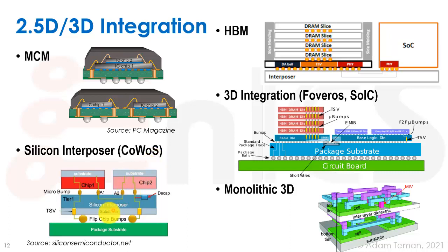So what you do actually is you have your package substrate, the regular package substrate, just like this one over down here. But on top of that, you put what we call a silicon interposer. So this is a VLSI chip. This would be in something like 65 nanometer technology or something, and it is not used for creating logic. It's only used for creating interconnect.